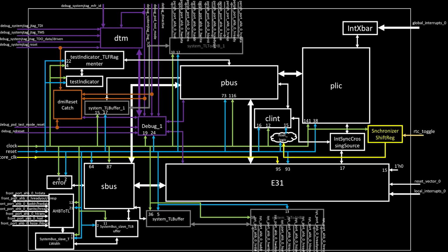You see the debugs. There was a debug line. So the debug line has to sit physically close to P bus so that the delay between the debug and the P bus, and the latency, is well maintained. I'll show you one of the timing paths which clearly tells how critical the path between debug and P bus is. That's basically more of design knowledge. The one who has very good design knowledge decides which block should be placed physically next to which block; that decision needs to be made by a physical design or floor plan engineer, and that's what we have been doing at the back end apart from the regular coursework.